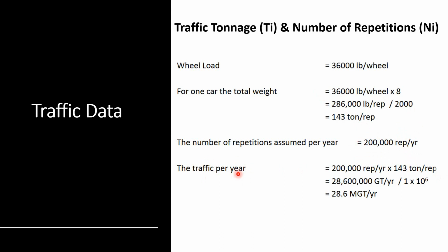Very important parameter. And it's very important because it helps you classify how critical the railway embankment you're dealing with is. Usually up to 5 MGT, million gross ton, is considered a light application track. Above 5 is considered one of the more critical or heavy track applications.